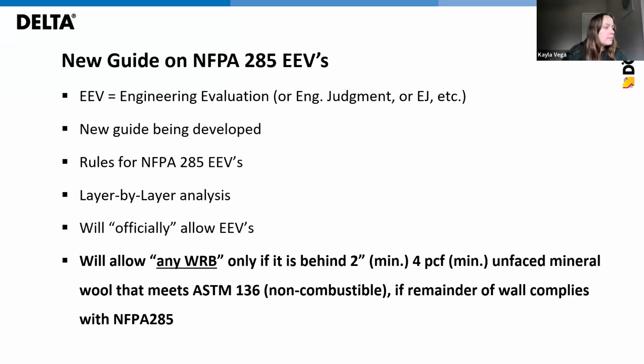All right. Okay, so here we go. This person wants to know if you can provide vapor permeability ratings on your air barriers. They said, I'm working on a hot, humid climate zone and need to ensure proper vapor transmission through the wall assembly. Yeah, so our products can range anywhere from approximately 30 perms up to 300 perms, depending on the application and depending on attachment method. So wide variation there. And that's based on dry cup. Wet cup, it's even higher. It would start at about 50 perms. Okay, wonderful.